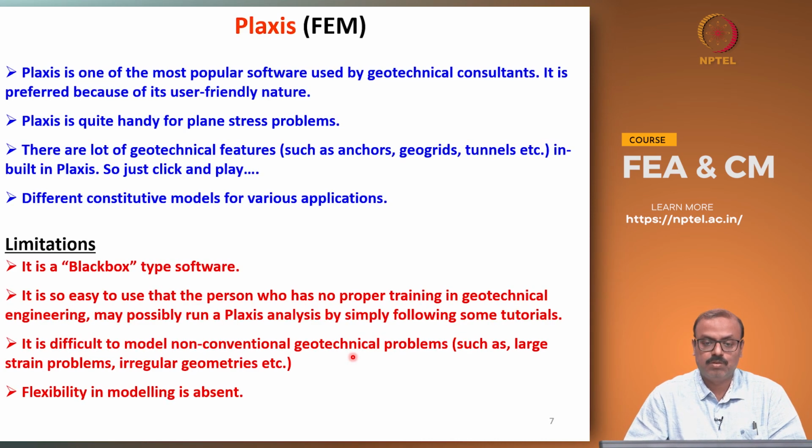The most popular, there are many more. I am just listing some of the most popular ones. We start with Plaxis, which is a finite element based software. It is one of the most popular because it is extremely user friendly and it has a certain number of geotechnical features like anchors, geogrids, tunnels inbuilt, so that you can just simply click and play. It is not general purpose, it is meant for geotechnical applications. So, that is why it has various types of constitutive models which are suitable for soil.